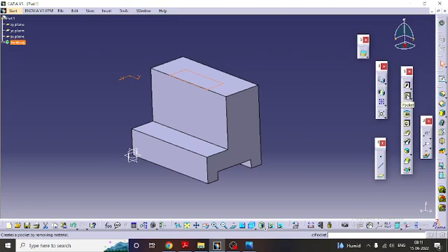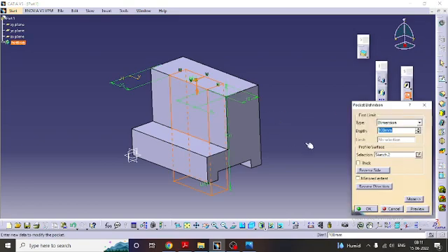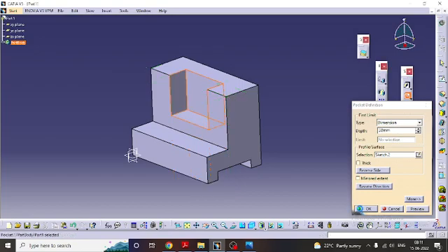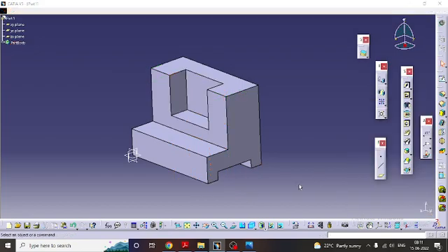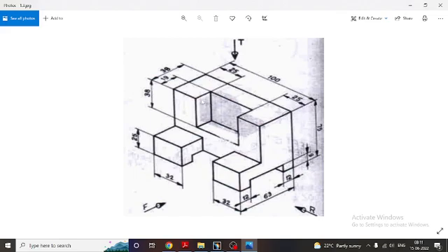For the pocket, how much distance do you need to give? This is in the down direction, it is 100. It takes the previous value we entered. So now you change this to 38. Then give OK. Look at the model now, you got this pocket, right? This is the 50 by 19 rectangle and the depth is 38.